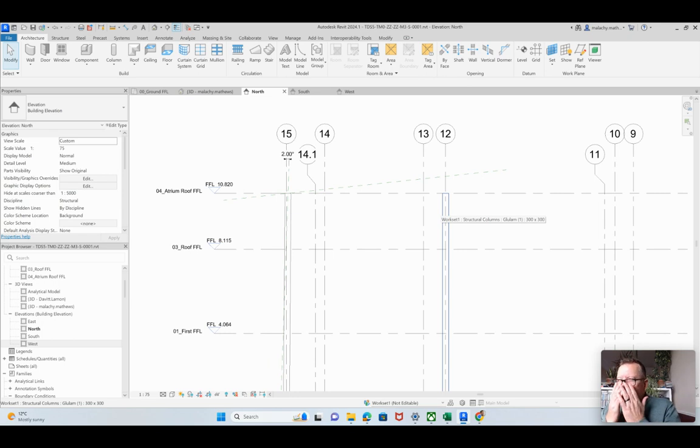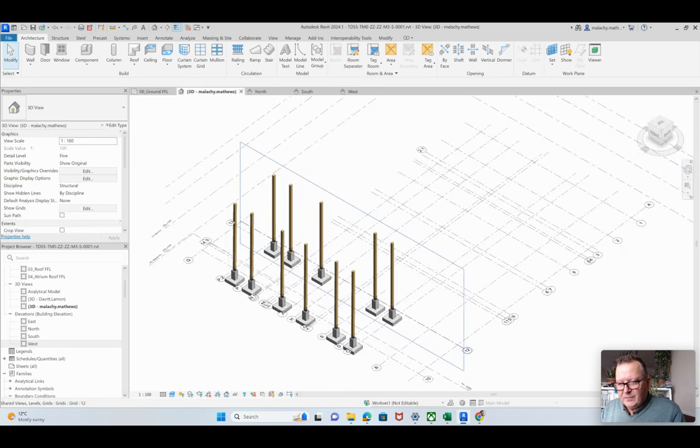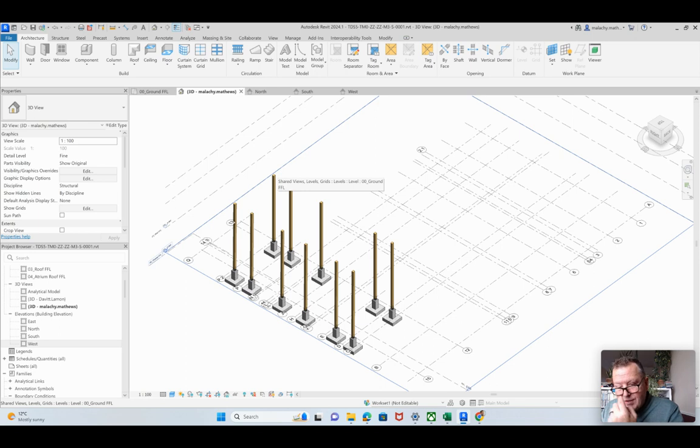So there's a couple of ways we go about it. Do it this way. All these choices that we have to make. We could create a slope in the roof itself. But the way I'm thinking about this is that I'm thinking of using a joist style here, where it's a posi joist or timber joists or flitch beams or something like that.